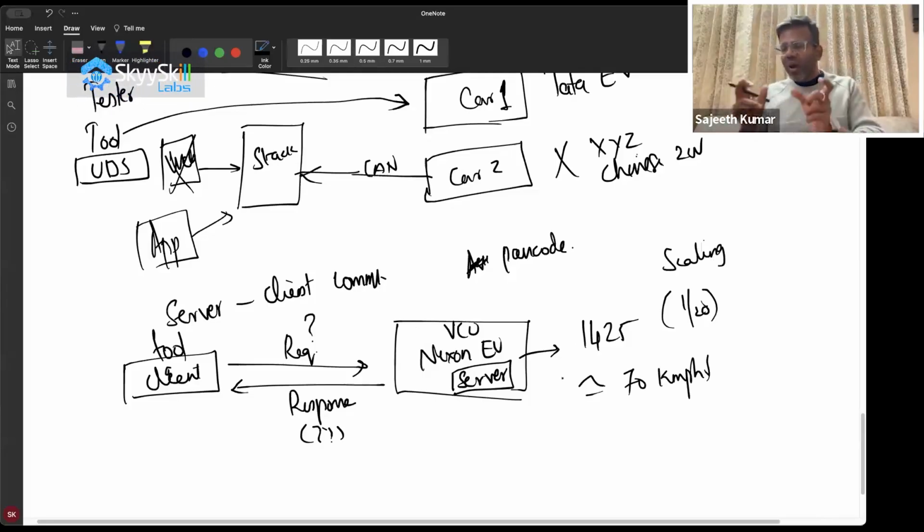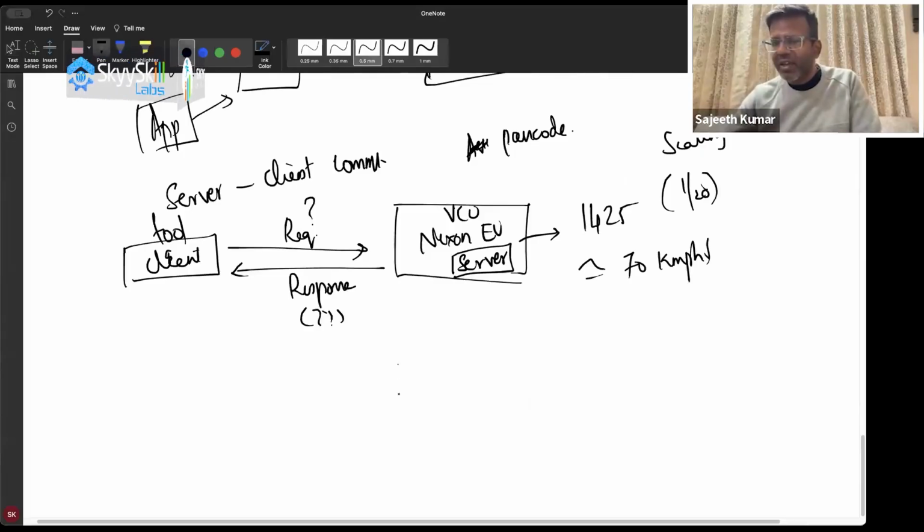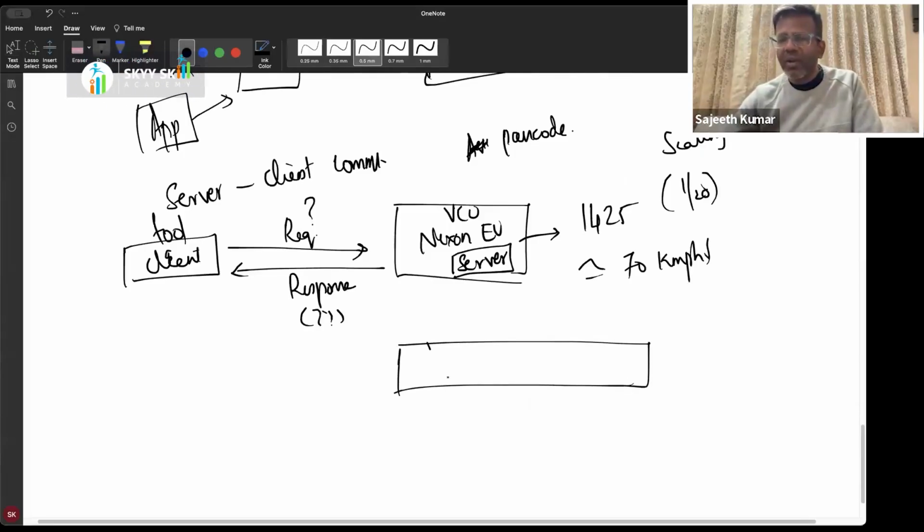And one single message might have multiple signals. You know that CAN is basically packaged signals, right? So one CAN data frame, right? I'm just taking the data frame alone. It might have multiple signals. There could be speed here. There could be the odometer, right? There could probably be a fuel efficiency figure which comes here.